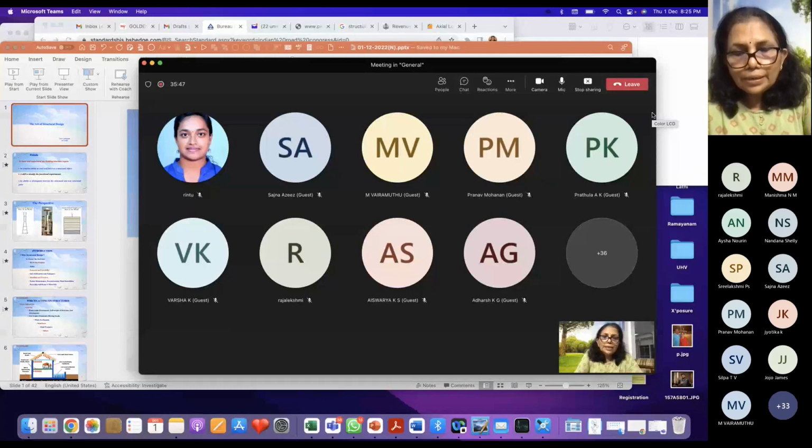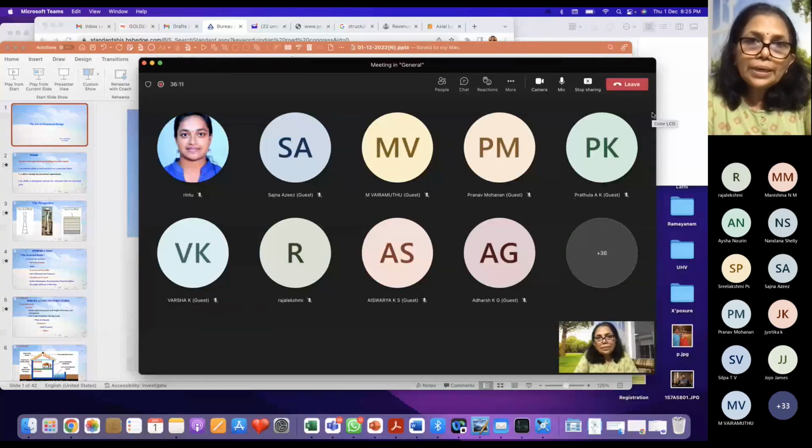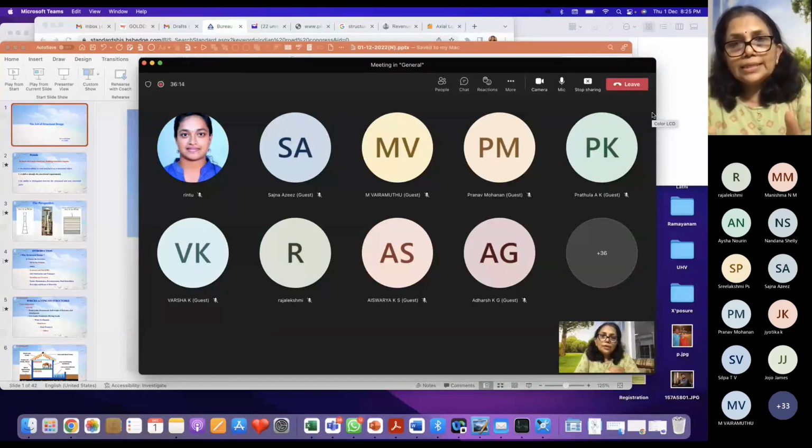So basically, the bending moment, shear force, axial force, all these are stress resultants. The stress is developed, and because of this stress developed, there will be a resultant for the stresses. So those are the bending moment, shear force, and axial force. And once you know the bending moment, then you have to find out what proportion of section you have to give to resist that. That is called design. This is in general I am saying.